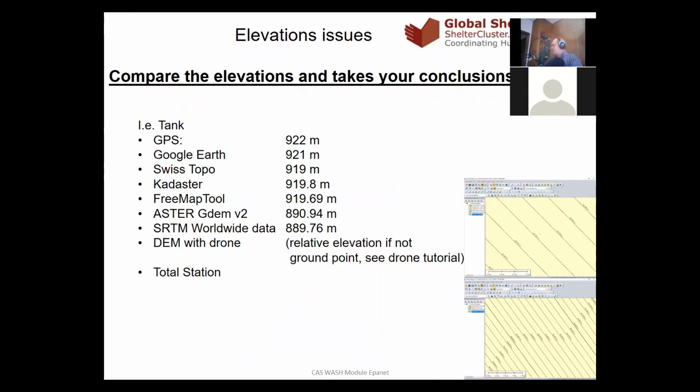Based on the previous elevation, I put all the elevation together, and then I see that there is a big discrepancy between GPS and the SRTM model. So if I assume that my cadastre is the most precise elevation, then I can really say that the Free Map Tools gives the best elevation. But this is for Switzerland. You should do the same exercise in Syria, and you should decide which way gives the best elevation. But I wanted to tell you that the elevation is very...